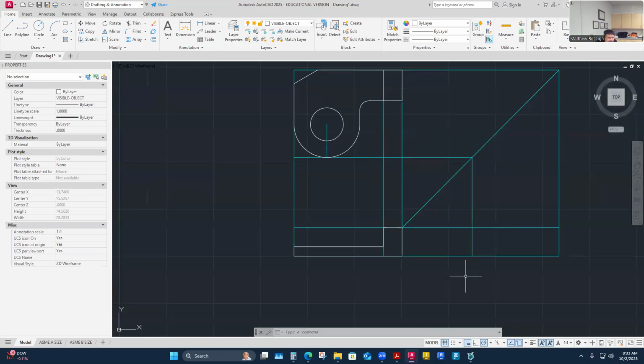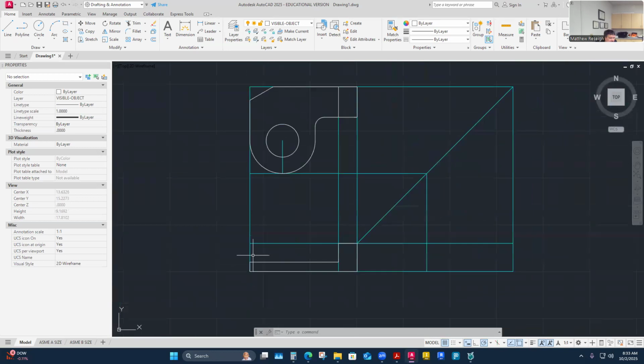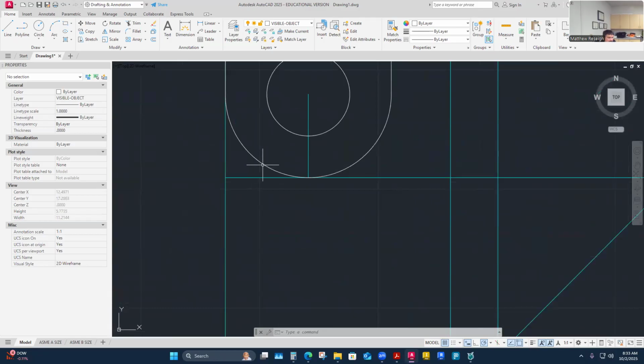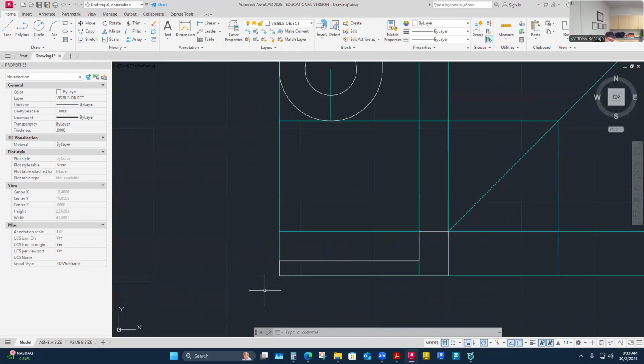I don't know what other details. This will be the first time I've drawn it in this position, so I might mess up a little bit, but I don't know what other details I have here. I think I'm ready to, yeah, maybe use my right side view. I should be able to see some of the radius here though, so I feel like I could radius this. If I was looking down along this way, this is part of that radius edge right here. And really, I could probably offset this line to show the radius in the top view. That's a detail that I think now I'm looking I could add, but this will also help establish it.